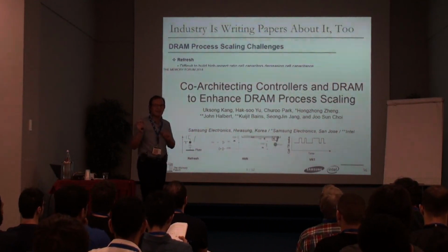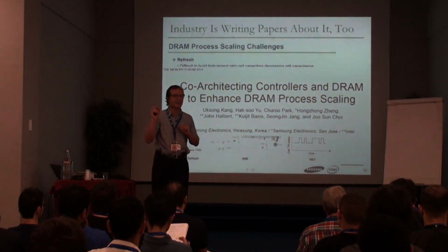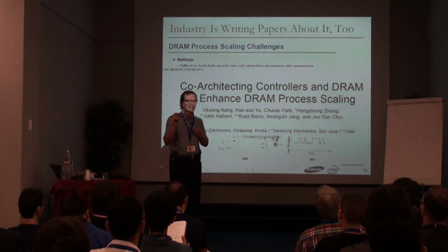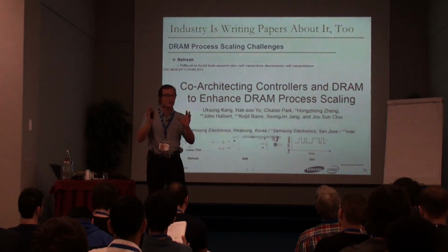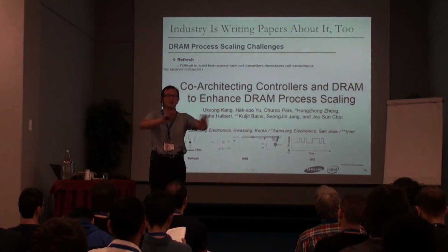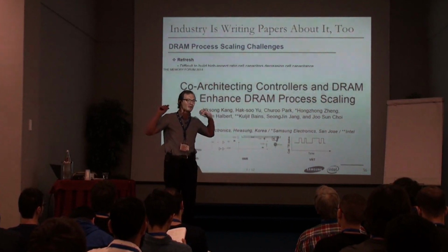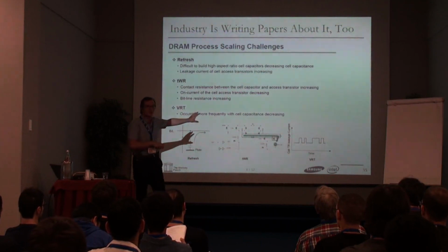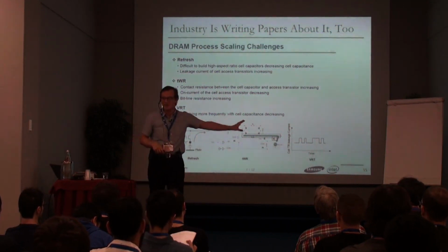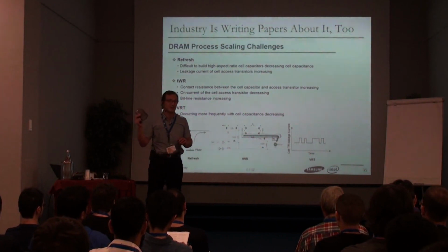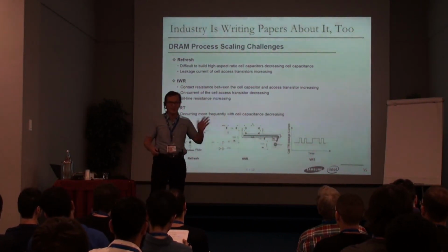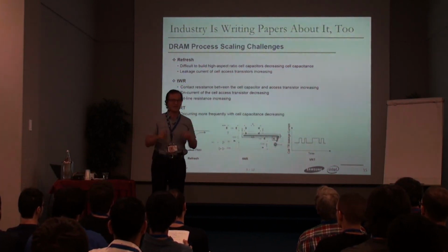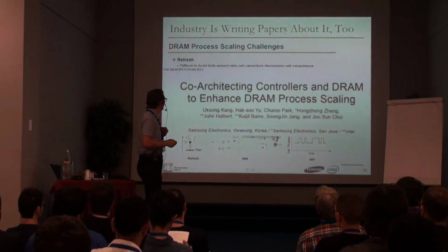By the way, variable retention time is interesting because it's a random error. Error correcting codes are a good idea to solve that kind of problem, right? Whenever you have a random error, an error correcting code that's applied uniformly across your entire device is helpful. And that's exactly the reason this paper also proposed, since we're having difficulties, we should put error correcting codes inside our DRAM chips. And that's exactly what's happening in existing DRAM chips. As I said a couple of lectures ago, I think, if you buy a cell phone next year, you'll definitely have error correcting code DRAM inside it.